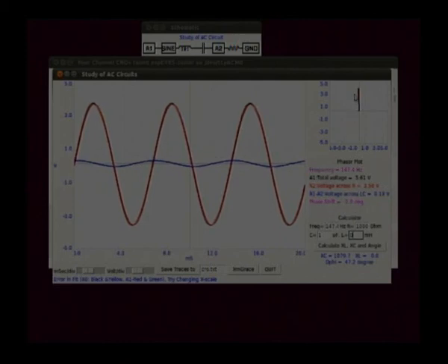and earlier the current was leading, now the current is lagging, but it is not much because the ratio between the capacitance and inductance is not quite high. Now you can do the calculation, because this inductance is around 55 millihenry and there is no capacitance in the circuit. If you make the calculation, the calculated value is minus 2.9 and it is tallying very well with your measured value.